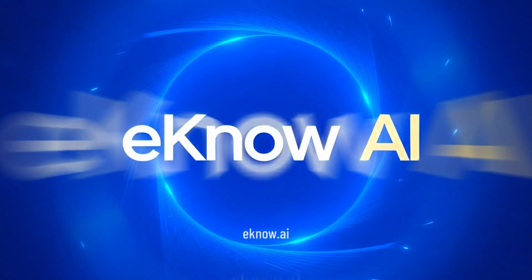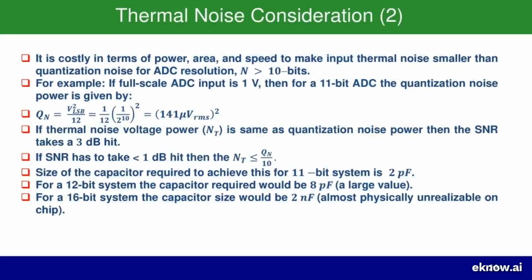This page continues our discussion on thermal noise, looking at the very practical challenges it creates, especially when we want to build high-resolution ADCs. The main takeaway is that for ADCs with a resolution higher than about 10 bits, it becomes very costly to make the thermal noise smaller than the quantization noise. And when we say costly, we're talking about three critical resources in chip design: power, area, and speed. You often have to sacrifice one to improve the others.